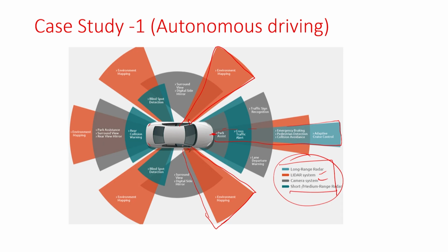These sensors I have placed here, plus you have 360-degree cameras everywhere. You have something here, something here, even here, even here, which will give you full 360-degree protection. This is a very high end vehicle that I am talking about. A normal vehicle will have at most, or at least, 2 short range radars here and 2 short range radars there. But even so, you have 4 cameras along the whole vehicle. Here also there is a radar. So you have seen the back side is also covered.